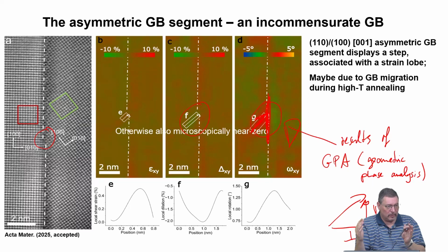So in total, the material is force-free and local forces counterbalance each other, right? You have this stress field, but the stress field of a dislocation is symmetric, right? So you have compressive and tensile regions. If you integrate in a sufficiently large region surrounding the dislocation core, you will again get stress-free.